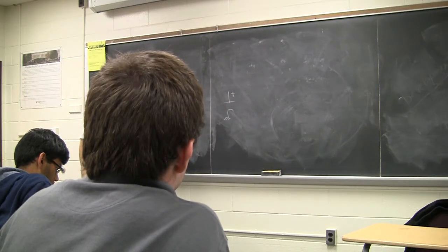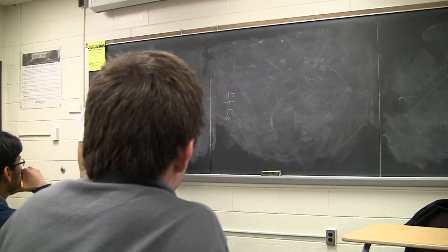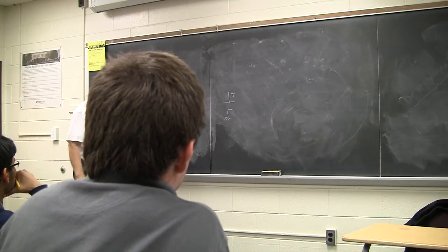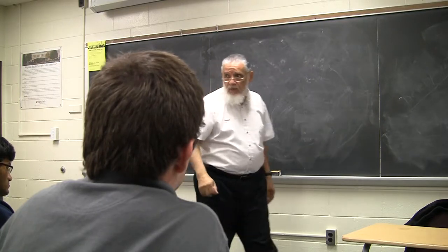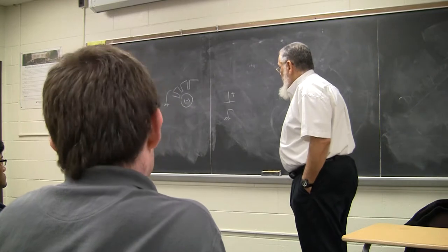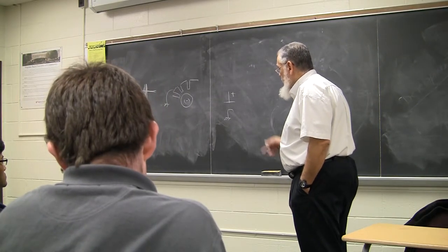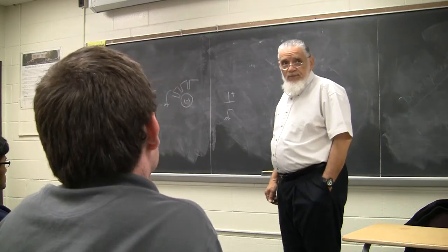Because of the magnetron construction, as you can see, the body here is really the cavity itself. So you make that the ground and put the cathode at a negative high voltage. That's the situation. Now, if you're sending a pulse signal like this in a waveguide, what happens?